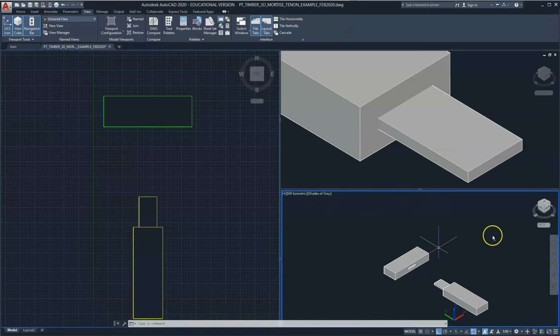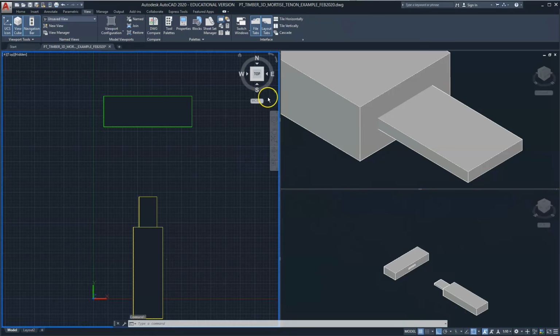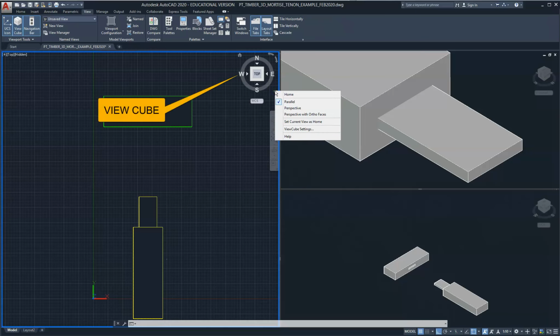Then in terms of our views, we should generally try to make our views parallel. I'll just show that there. We've got this little thing, kind of like an inverted eject button, and when we click that, we can get either a parallel or a perspective view. Generally when we're drafting, we want a parallel view. And then this drop down here is for the world coordinate system.